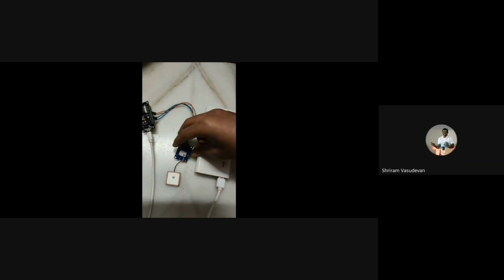Now the most important point to remember is that the GPS sensor will not give you correct output when you are keeping it in-house. So please remove the USB cable from the laptop and connect it to an external power source, that is your power bank. When you take it outside, you can get the GPS feed, and the feed will be updated in the Adafruit cloud. This is because closed space connections do not work with GPS, and you will not get data when you are working in a closed space. That's the reason we have removed the power source and given it a new power supply through our power bank.